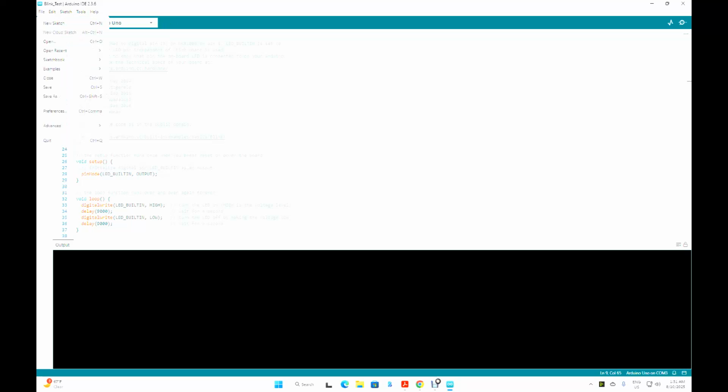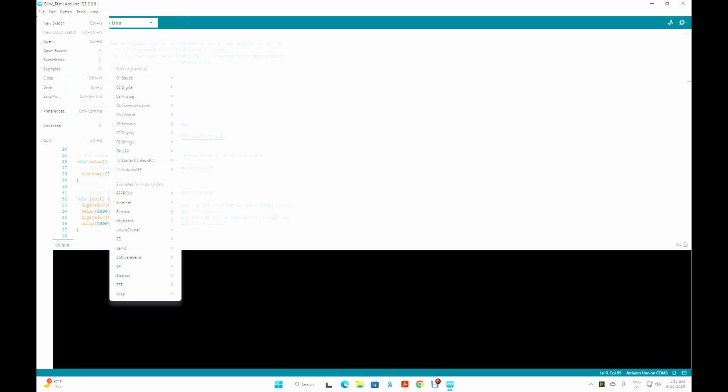So the next thing we're going to do is use this Arduino IDE, version 2.3.6 in this case. It comes with samples, so you can go to Examples. For the first one you can do Blink as a sample, but I want to use a string example, because that way you can see on the screen that we're actually uploading code to the Arduino board.